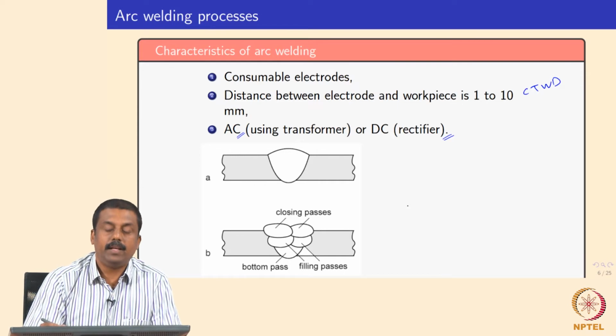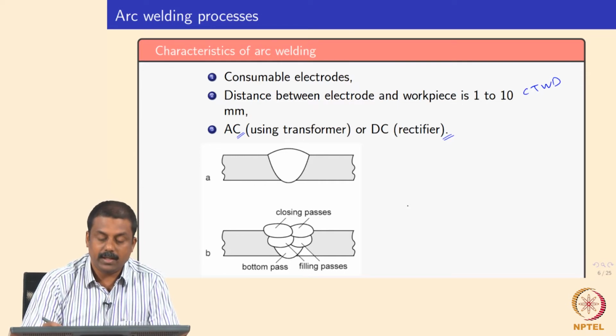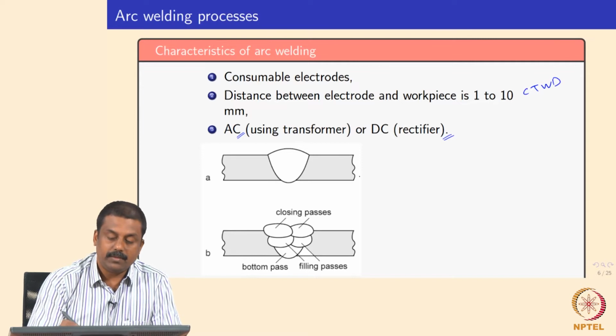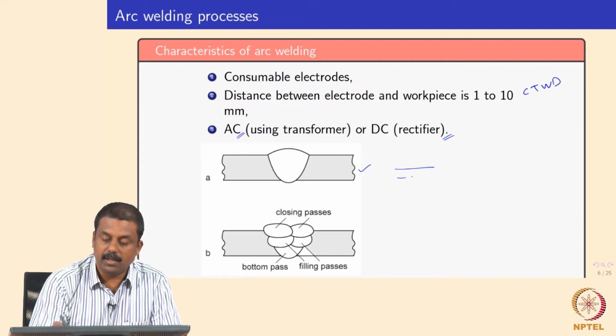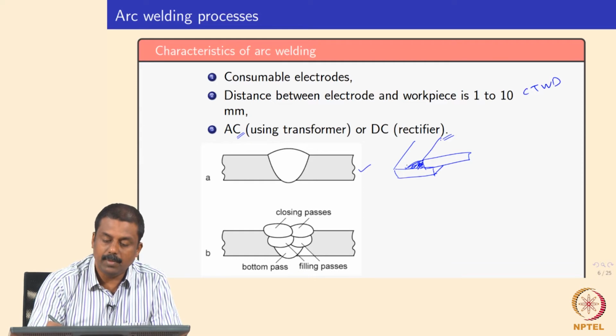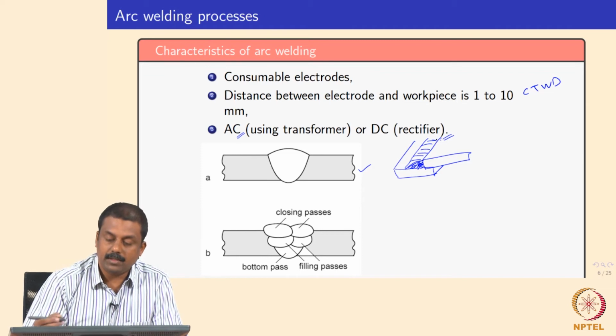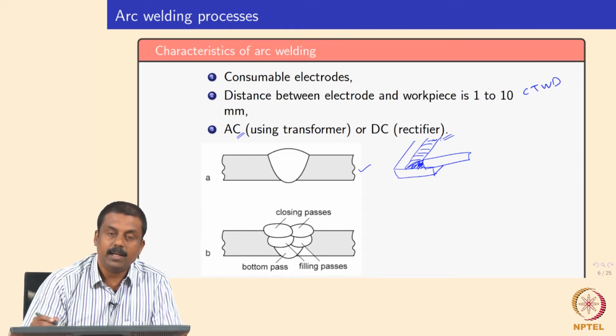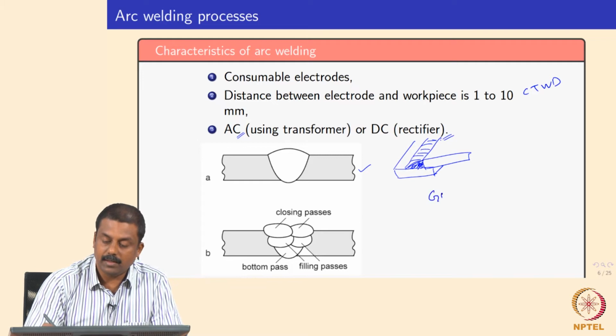Generally in welding of automotive steels, if you are using GMAW, in most cases we will be doing a single pass, and in some cases we may also have to do it in an overlap configuration, like in a lap joint in a fillet mode. This is the most preferred mode of welding, especially if you are doing GMAW brazing.